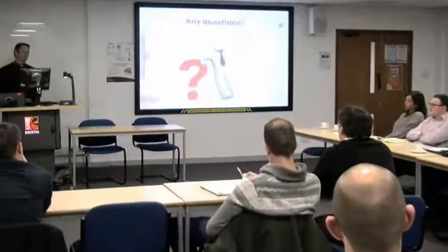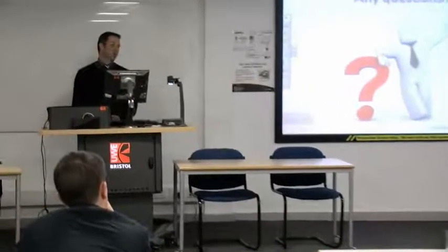Obviously the structural and the architecture, you're not really going to move that, so it comes down to the M&E bits really. A lot of the jobs we've done, we've done both M&E, so we've avoided that problem. With other jobs, we try to do it as if you're installing it on site. So you put your ductwork and your pipework in first, and we would let the containment be modelled around those elements, and you get the lighting in, and then we'd put the grills around those.